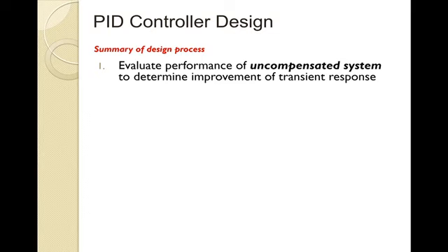So again, say you have a compensator. Let's actually draw this, similar to what we saw in previous modules. I might have a reference, R of S, right here, and some feedback, negative feedback typically. We're going to have our compensator, GC of S, as shown here. That will then feed our plant, which we typically call G of S. Typically, what we've been doing is having unity gain feedback.